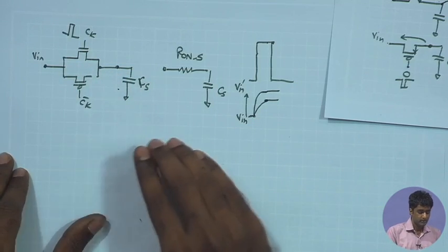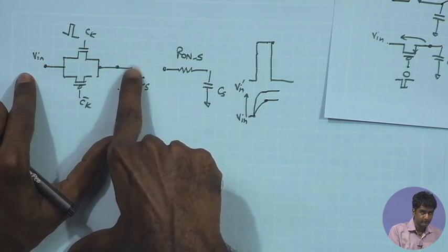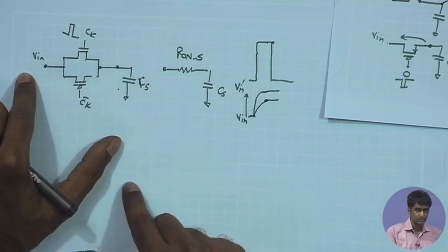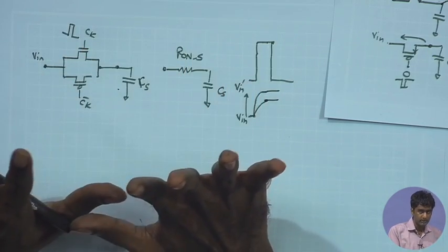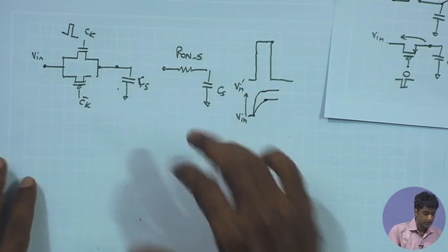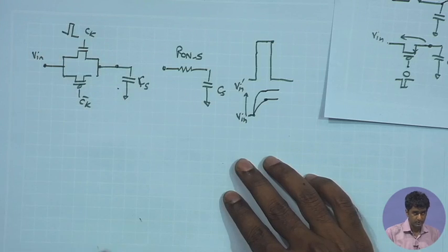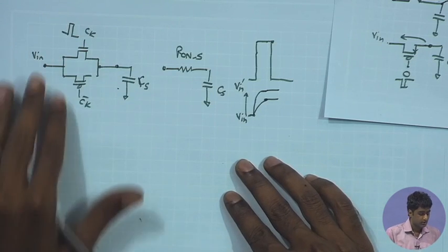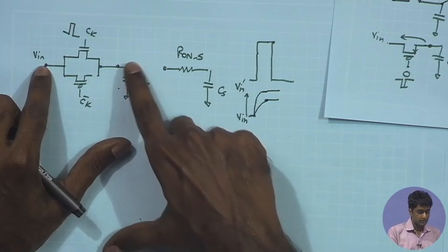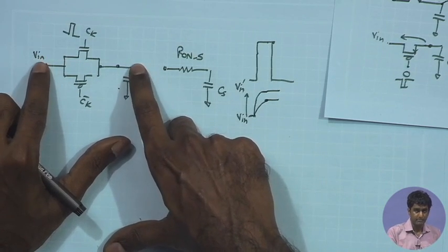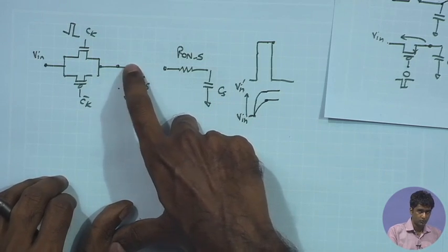So, the ideal functionality is that during the on duration the input signal should be faithfully replicated on the CS as fast as possible within that on duration, and when the switch is getting off, the signal stored over here should remain stable, it should not change significantly. And we need to see what is the effect of the nonlinearities of the switch on this expected behavior. To do that, we can first of all look at the off duration. For example, what is going to happen if the switch is getting off, and what is the behavior expected for the signal stored on this CS.